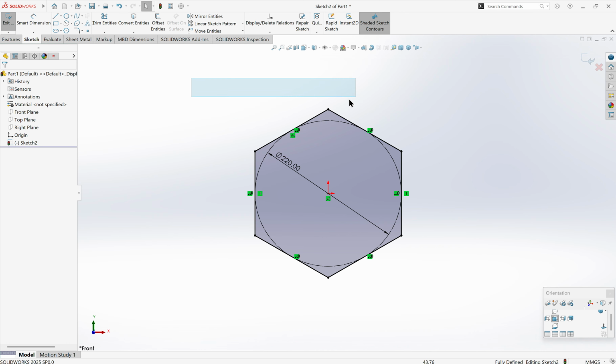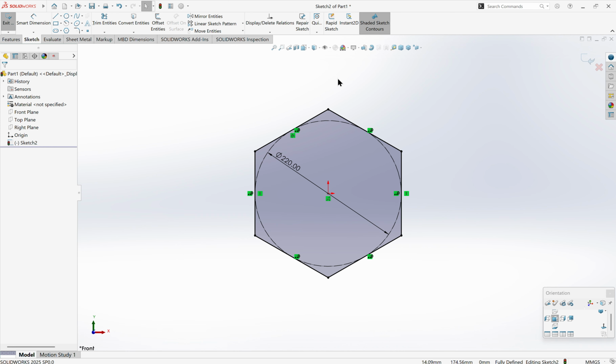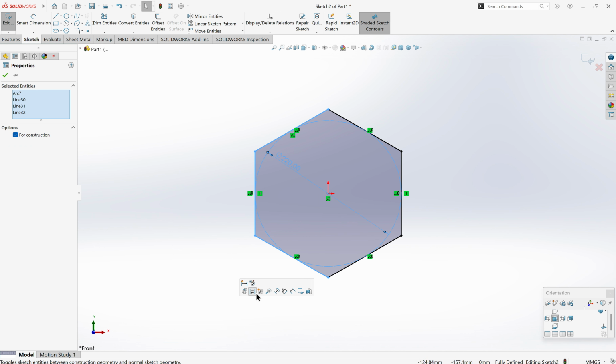It's not going to select this other line too. But if I do it with the green box, from right to left, it's going to select this line with this line and with this line too. So what does that mean? The blue box selects only the fully selected things. The green box selects the things that you have moved over or hovered over.